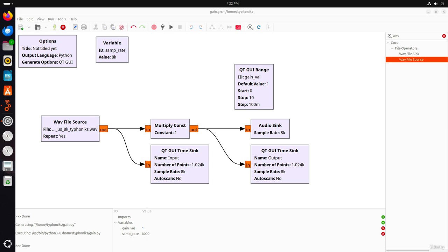The operation of a low pass filter revolves around a concept called the cutoff frequency. This is the dividing line between low frequencies and high frequencies. The low frequencies are the part of the signal that passes through with minimal change, and the high frequencies are the part of the signal that is suppressed or completely removed.